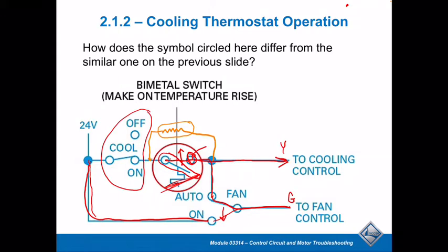The idea of that cooling compensator is, I would say, designed to prevent short cycling. It's trying to control the cycle rate to some extent, but in a fixed manner. So basically when it's off, it's kind of saying, hey, it's getting warm in here, so it's going to allow the cooling system to turn on a little quicker.